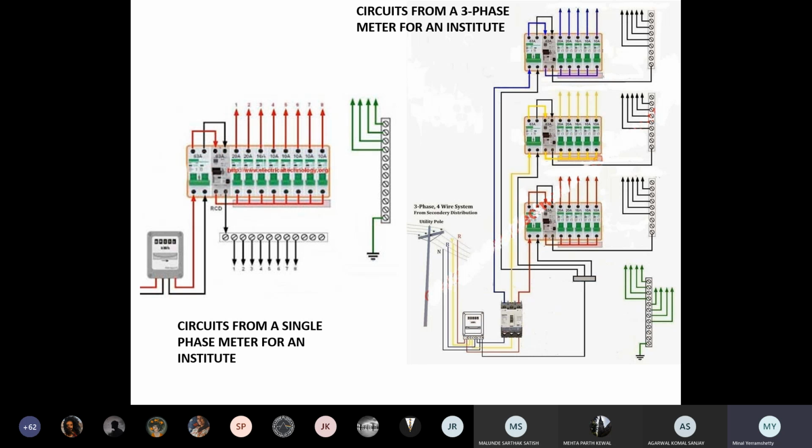So you see that overhead line from which I am taking the line. Obviously, I do not take. Please, this is completely wrong. But this is what happens when you take diagrams from the internet. Okay, do not show like this. The line always comes from the feeder pillar because the voltage of this line will be 11,000 volts, which I don't want to shock my entire building. So you will need to show me that the line is coming from there and it's coming from a feeder pillar, or instead of that you have to show a red box.